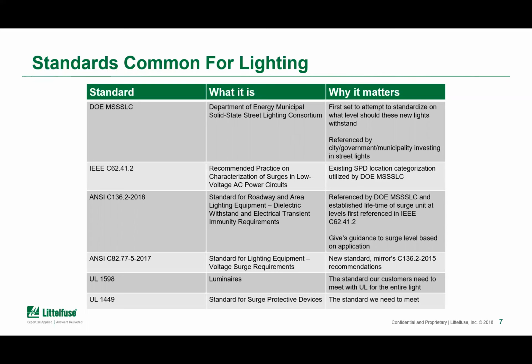One of those would be the ANSI C136 standard, which is specifically geared towards roadway and area lighting equipment, or outdoor lighting. It pulled from both the DOE spec as well as the IEEE spec and developed the requirements for testing or evaluating lighting fixtures against transient energies.